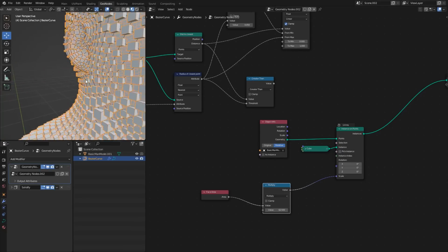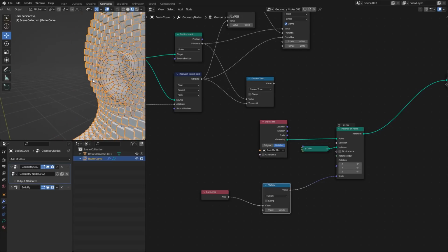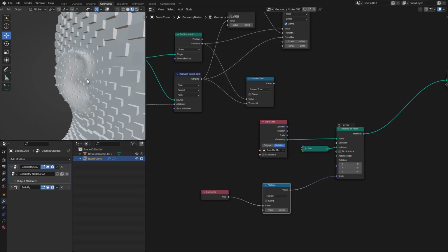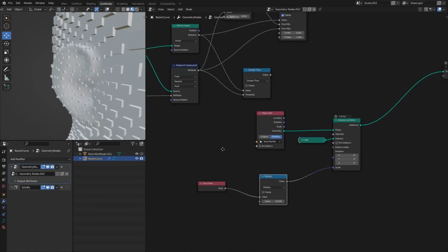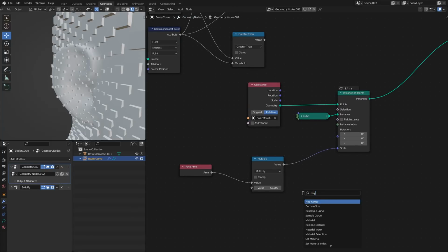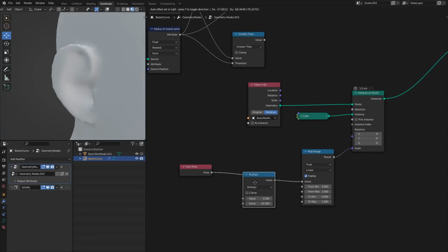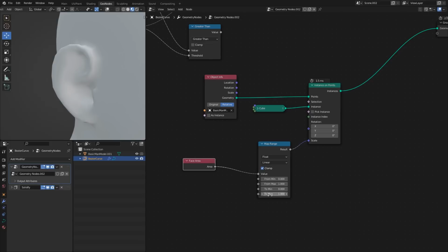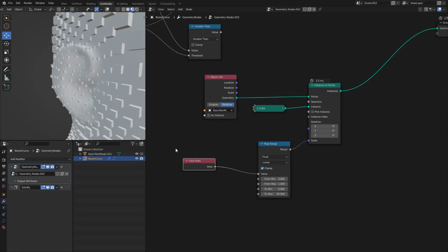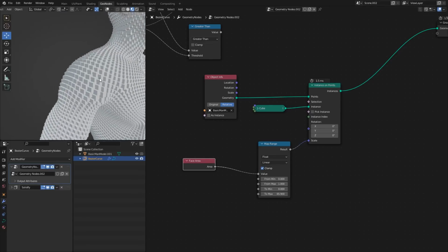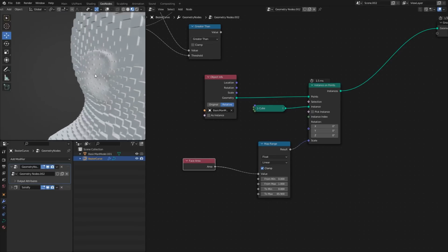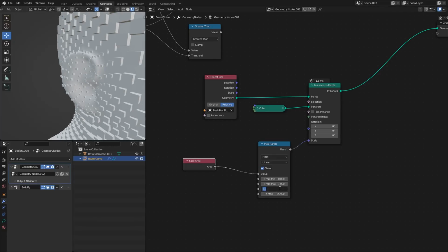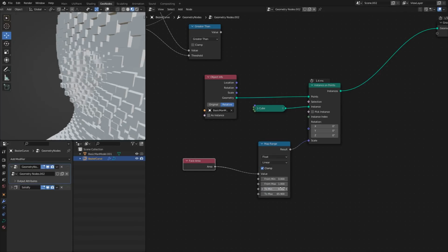However, you realize over here where we have very tiny faces, the cubes are way smaller than they need to be. To fix that, we will just use a map range instead of a multiply node, and then we will set a custom maximum so that the big faces look fine, but also now we can set up a minimum, which has to be pretty low, 0.001, and that will let us scale the smaller faces up.